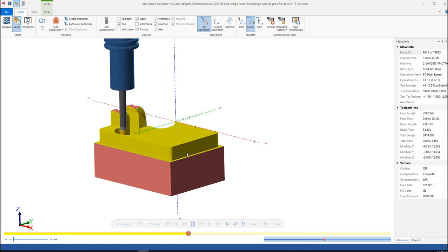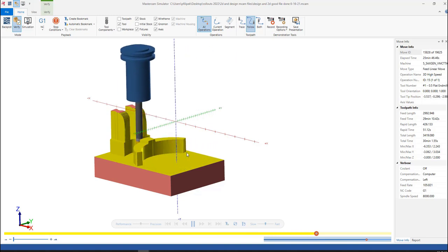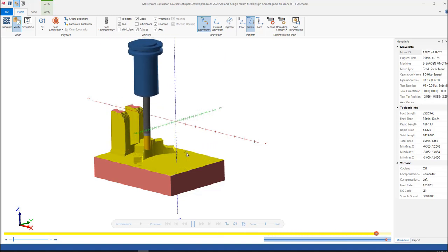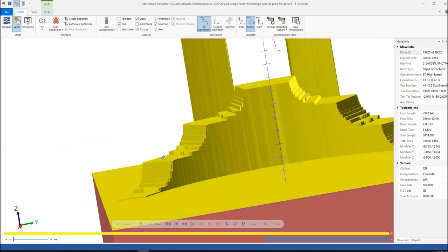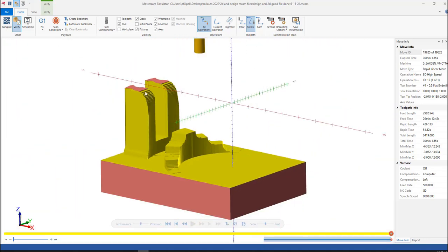So this has a lot of power. Typically we're cutting heavy down and then working our way back up for any detail. As you can see here, we only work 3 inches down, but you can see the nice detail that it did put on the part for us. If we wanted finer scallops on here, we would definitely just decrease our step-up value.